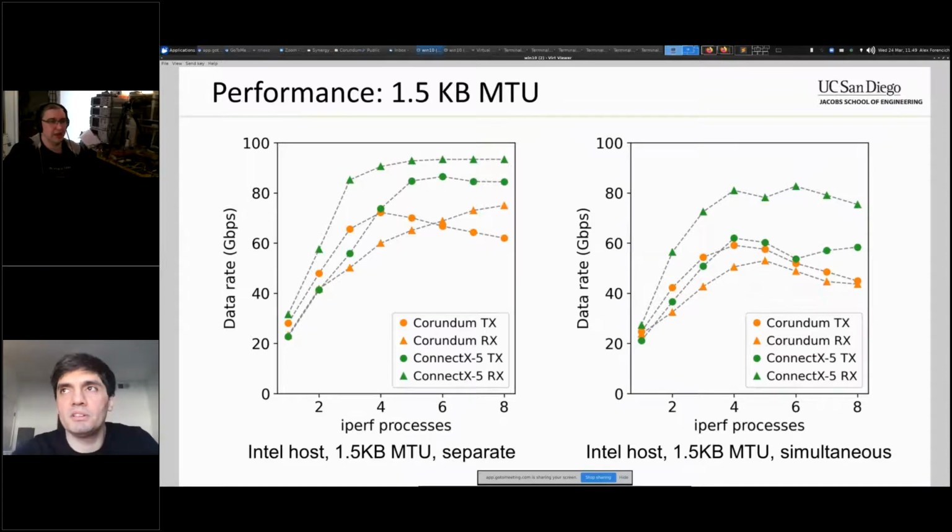1 picosecond, yeah. I don't know what that number is off the top of my head, but I was thinking, okay, if we're going to be updating this once a second and we want to be within a nanosecond, how many bits do you need? It's around 32 or so, so that works. And the core clock we're running this thing in is a 250 megahertz clock. So I will say there's probably some improvements we could make to the time synchronization.